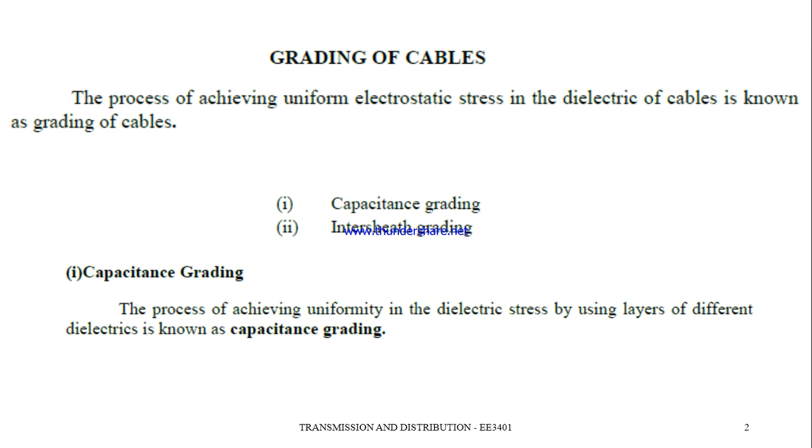So what is meant by electrostatic stress and why is it caused? Cables are nothing but a core conductor surrounded by insulation, over which we have certain layers of protection. While considering the insulation rolled over the conductor, stress may occur at the insulation level. What type of stress is going to occur?